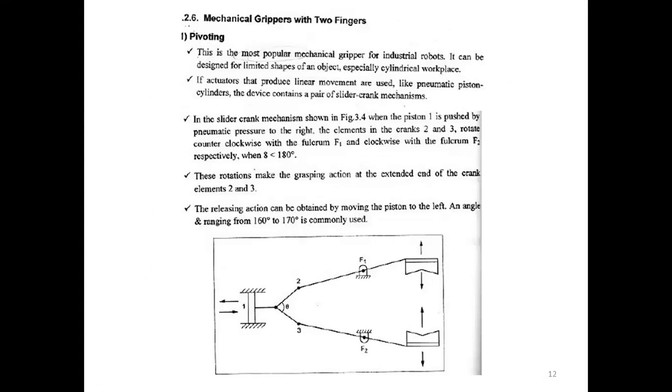Okay, so this unique feature, what will happen now? It allows the grippers to pick up objects from the inside, which proves to be useful in many situations. What are two finger grippers good for? They are better because they can grasp a wider range of parts and handle them with better precision, and the payloads are decent. But it will be complicated to use a parallel gripper when we are changing a part's size or geometries.